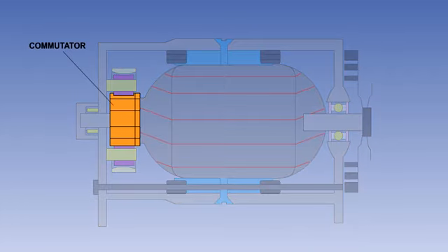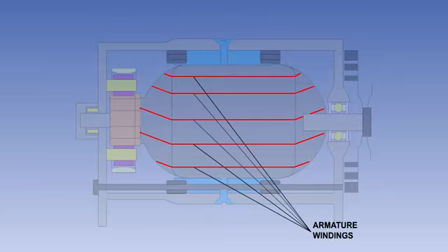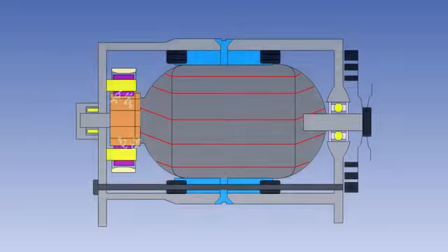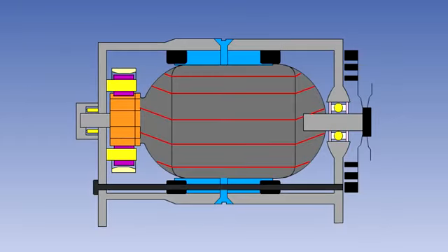When aircraft first began requiring electrical power in appreciable amounts, the only practical way of converting the AC produced by a generator into DC was by use of a commutator. But there are a number of problems with the use of a commutator. The heavy load-carrying windings must be on the rotating assembly, and because of the high current flowing, there is a lot of sparking between the commutator and brushes, causing the brushes to wear out quickly.